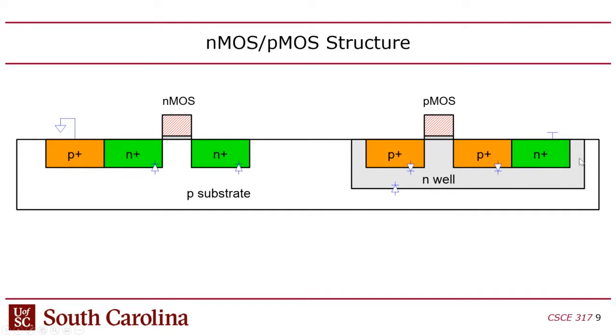And that's exactly what it looks like when you design a chip. You have to literally put these wells in. Now you might say, what is this extra thing over here, like in the NMOS, why do you have this P plus here? This is the way that you connect the substrate to ground. You'll have this little diffusion area connected to ground through a wire.